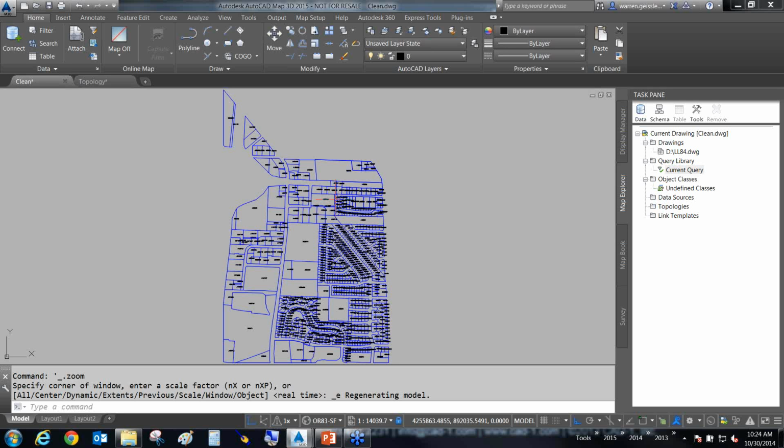Now, I'm glad Stan did mention something a little bit earlier. Stan said, okay, this will work with Civil 3D. Yes and no. It will work with Civil 3D or AutoCAD, but it will not, I've got to stress this, will not work with Civil 3D objects, alignments, parcels, survey points. It won't recognize any of those objects, so you cannot do this with Civil 3D objects. There are other methods you'd have to jump through, and we could train you on how to use those.